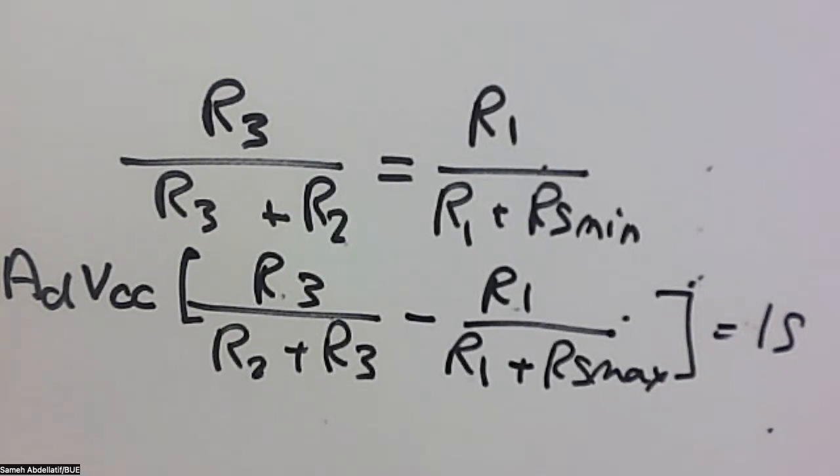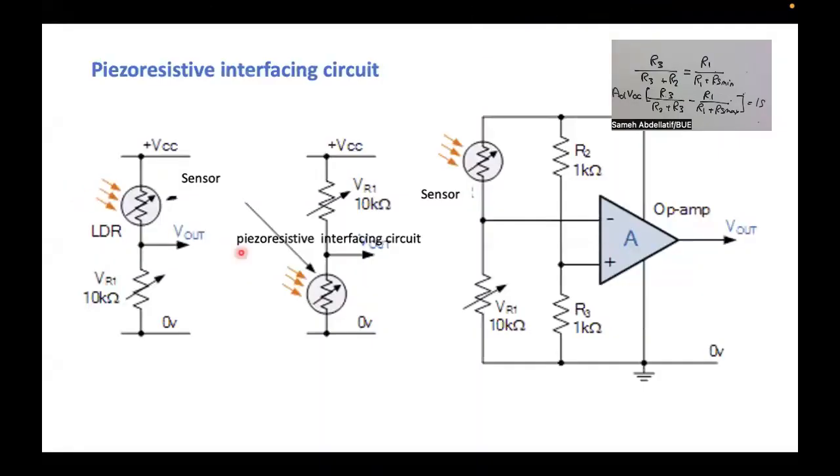Another added feature in this type of circuit is the use of the operational amplifier, because as you already know, my dear student, this sensor is now isolated since the operational amplifier input impedance is typically infinite, or realistically very high, so you ignore any loading effect in this branch. Additionally, this is now an isolated terminal because the output resistance of the operational amplifier is theoretically zero, practically very low. So again, you have isolated any loading effect for this circuit.